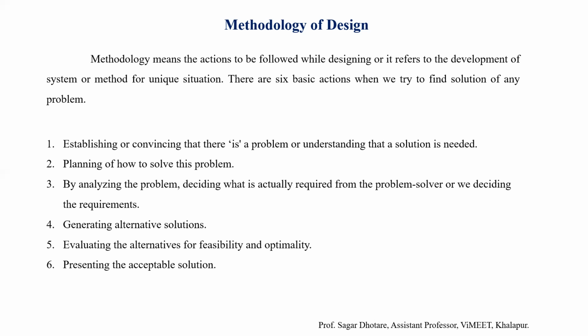Then there are other parameters for the tire, then the body. So what are the basic forces applied? What is the material? What should be the strength, rigidity, hardness, wear resistance, then fatigue strength? There are various factors which we have to consider in every step. Also, we have to understand the failure modes, and based on those failure modes you have to design a particular component. Okay, so in a few cases we design some parts purposefully for a safe fail condition,